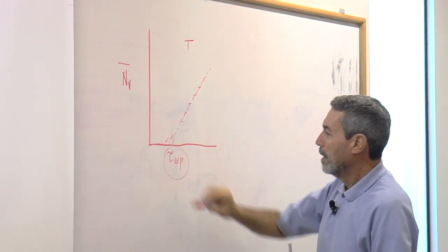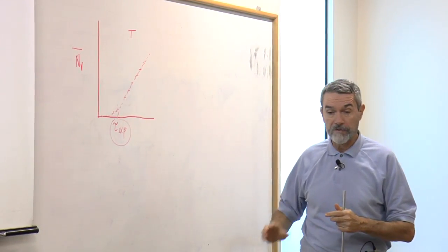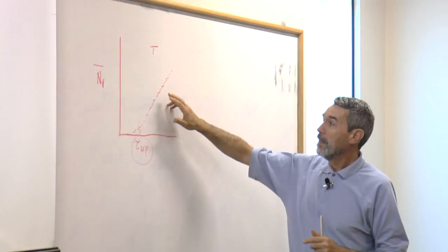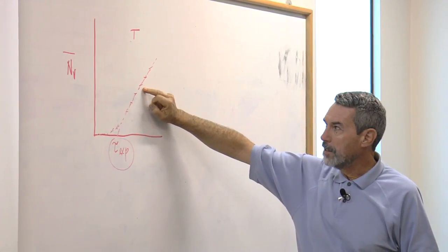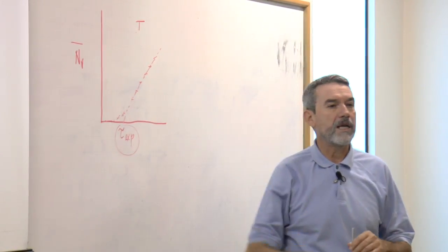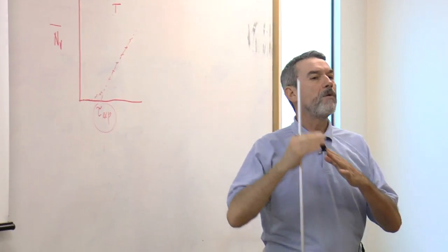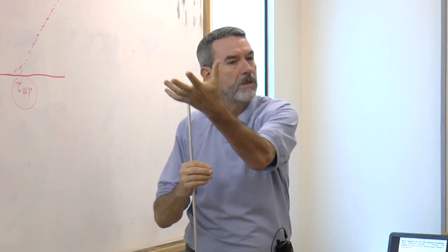However, this experimental tau is subjected to errors, very important errors, because in order to see the crystals that we count, if you recall the previous class, we normally use a double stage heat treatment. We first nucleate the crystals and then we grow them up.